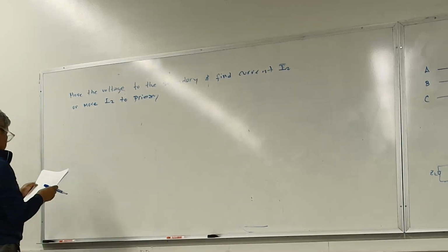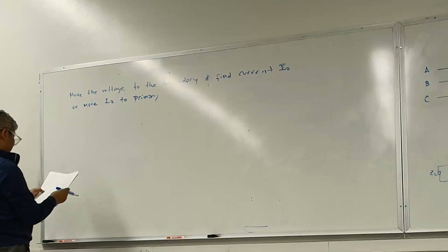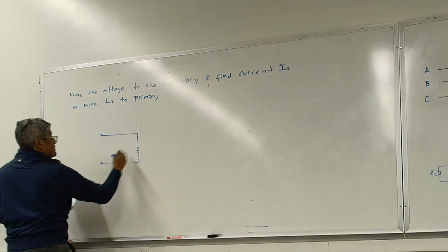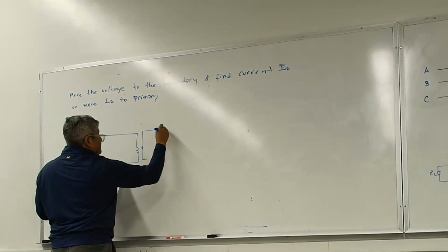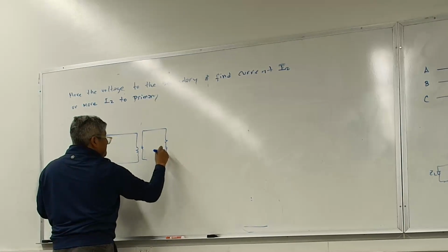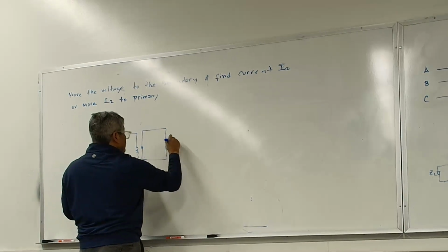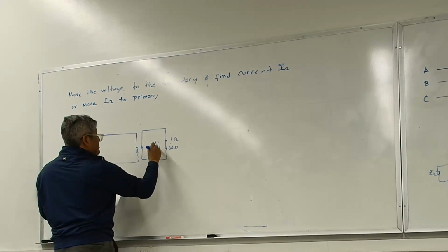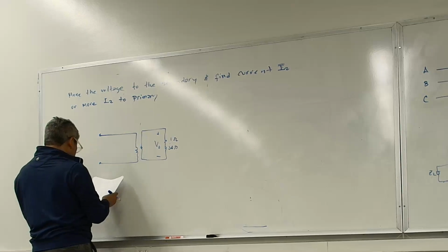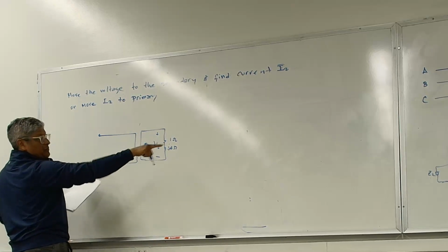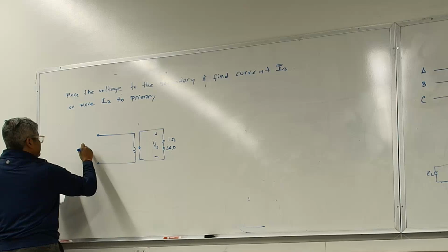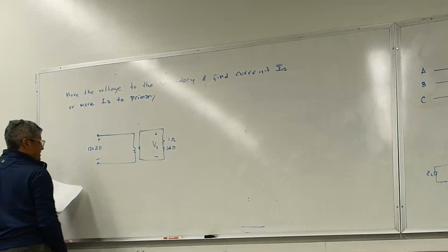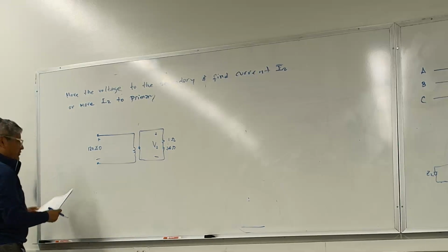Let's go back to the example again. So I have the little transformer right here. I have this impedance, and this was 1 ohm, 4j ohms, and then I need V2, plus minus. And from what we found out, the voltage here was 120 angle 0 degrees. We can say that, right? That was the primary voltage. So what is the secondary voltage?